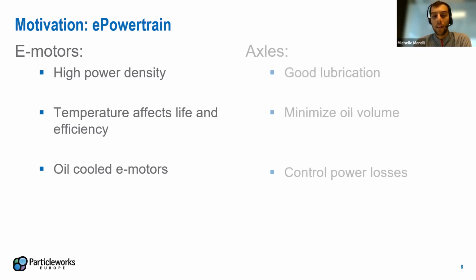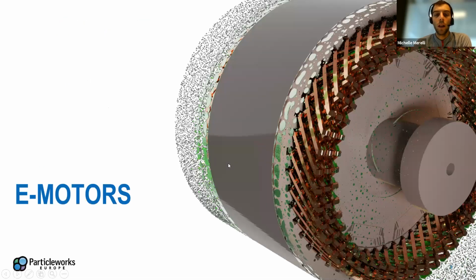in the most critical areas. And at the same time, we see that in the e-powertrain system, we have coupled axles in which basically the oil-cooled e-motor is transferred. So between the axle and the e-motor, we have transfer of oil with different solutions. And we have a closed circuit dealing with both cooling and lubrication. So let's start with the e-motor analysis and simulation.